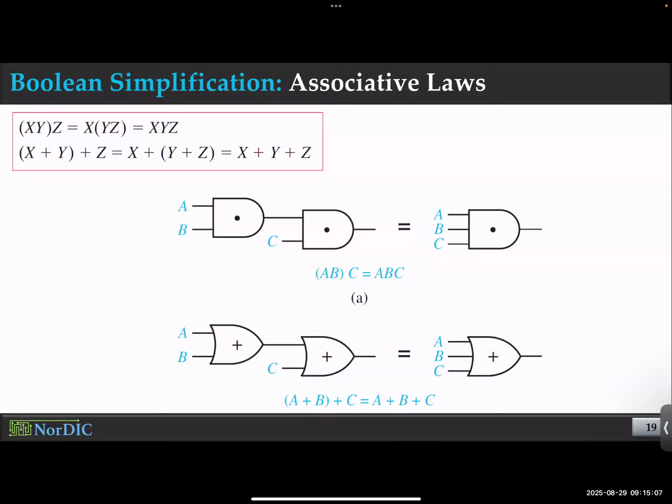It will go through all these steps, and chances are there is not one answer. There are multiple possibilities. So it decides on one equivalence based on what you're looking for. So when you optimize, you mention to the tool that, hey, all I care about is the absolute lowest area. So it minimizes area by all means. That means in doing so, it might make your circuit work slower, or it might take more power. So it doesn't care about anything else, just area.